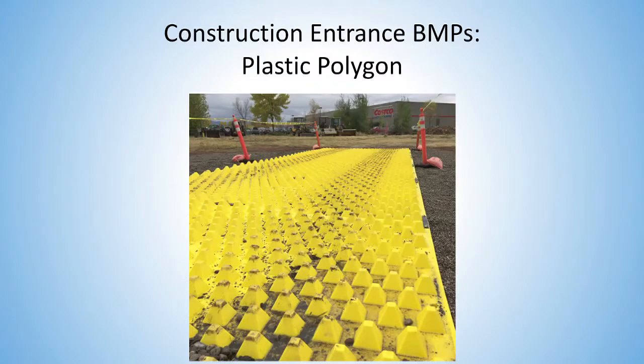The plastic polygons, the FODs, are some of the newer devices. They are a high structural plastic material that comes in segments, and again, they work better when you get a group of 3. I see some places that try to use just one. Again, it's kind of like you're sizing it a little short there, so you are going to have to be brooming the road a lot more. Make sure you follow the manufacturer's recommendations.